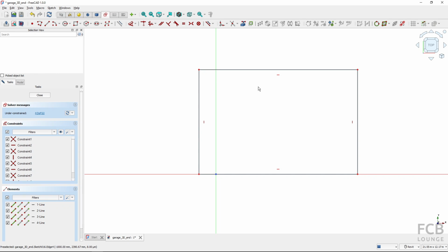Because I transformed this sketch from the rectangle, the only constraints are horizontal and vertical. So I would have to constrain this object, but here it's quite easy because I can use the coincident constraint. I will select this one, select this, and constrain it to the base, and now it's constrained.